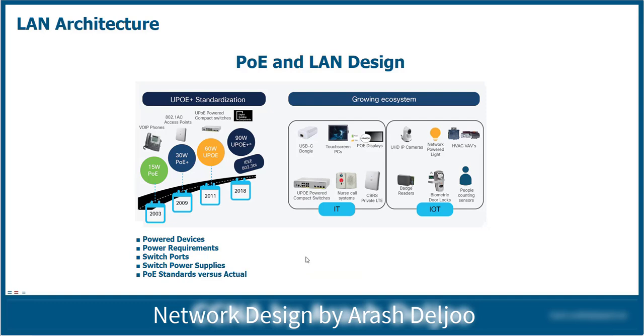Because of that, you need to first identify the PD devices that you have in your network, the number of those devices, okay, and finally you can choose a switch that can provide the power of those devices in each port, and the total power of that switch should be at least equal to the total power need of your devices.